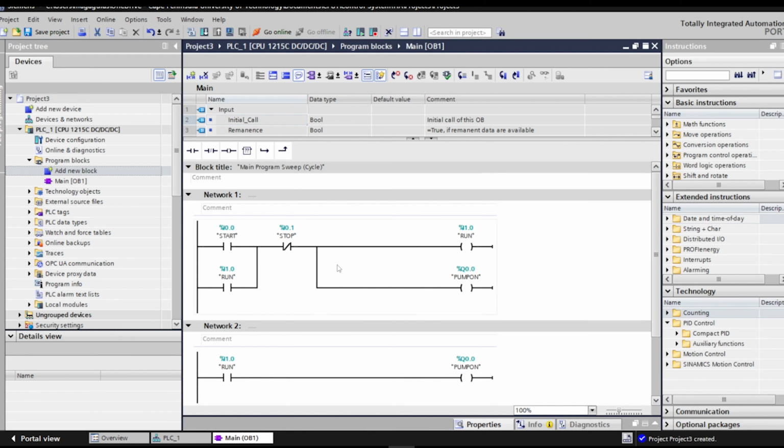If we delete this one, when this is energized, it will close this one and this one, then our pump will run. Then if we want to stop while our pump is running, we can press stop here. Then the circuit will stop, the motor will stop running, or we can put in timers and counters, and it will stop at the time you have selected. If you say it must run for so many seconds or a minute, it will do that.